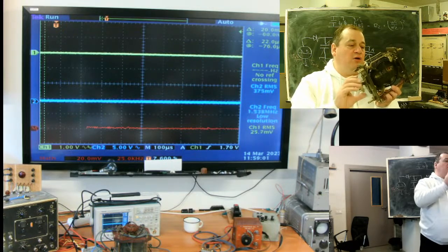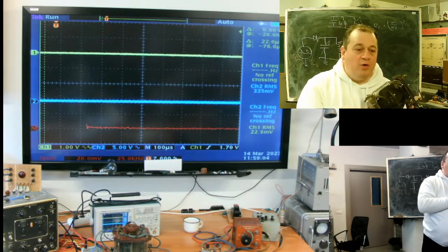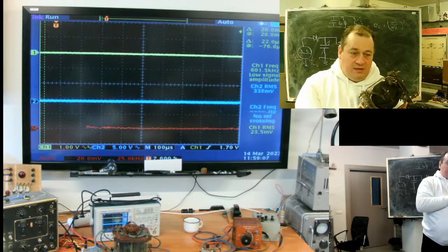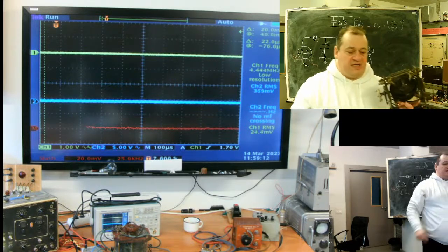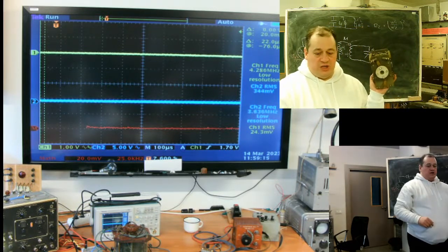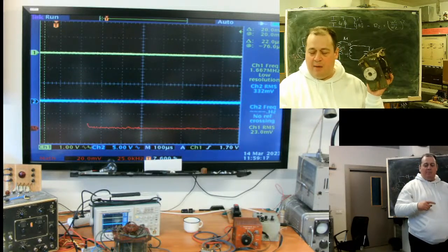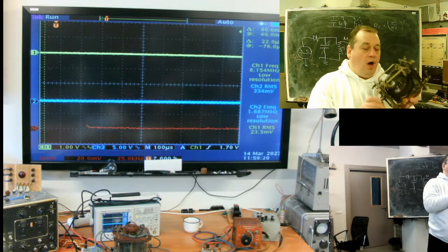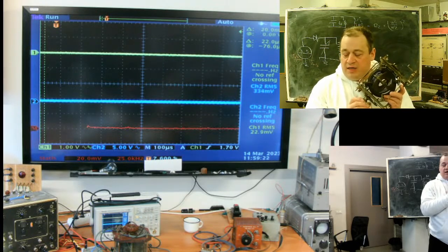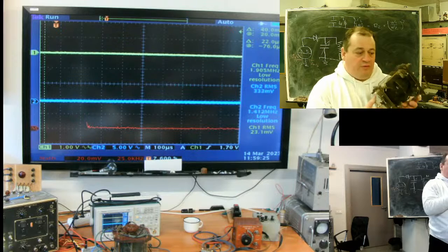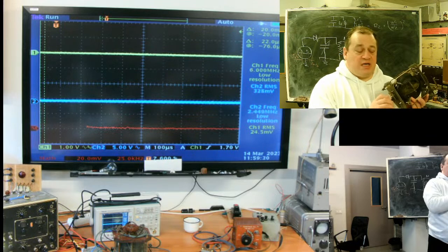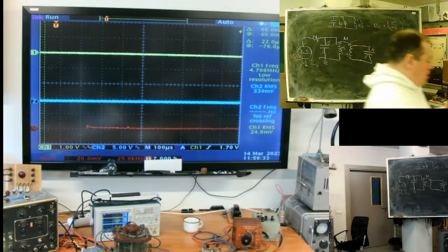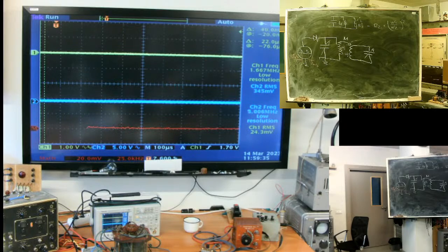It's a network, in reality, of variable coupling. I can use it as an inductance connecting both coils in series. This will give me the ability to change inductance plus minus double mutual. Or I can use it as an adjustable coupler. For example, such are used in transmitters to adjust coupling with the antenna part. It's a system with variable coupling.